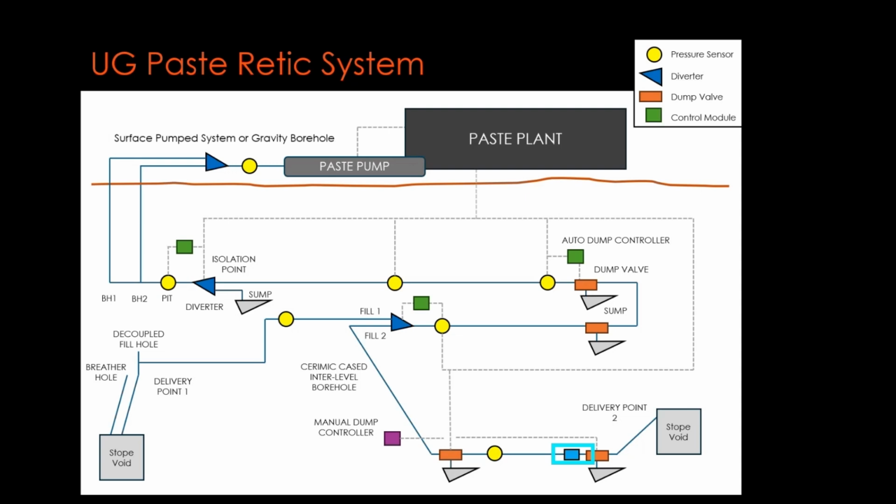So knowing that the paste is discharging at the correct rate during stope filling is an important operational parameter when making any planned adjustments. A low flow indicates that the retic may have failed and requires the underground paste crew to immediately investigate. This measurement is also used to indicate a successful flush of air and water has been achieved. This is a critical control when pouring over shift change and that no one is available to be in attendance.